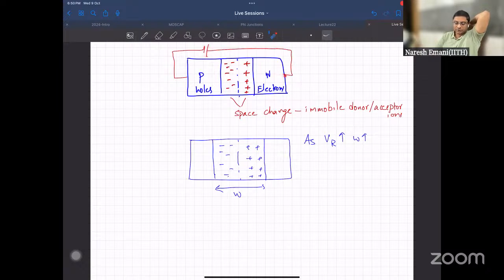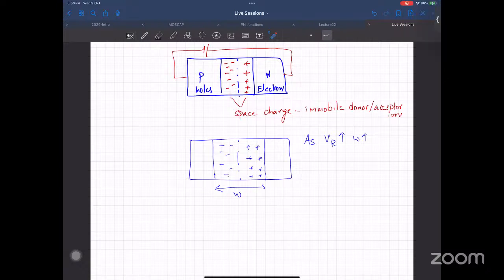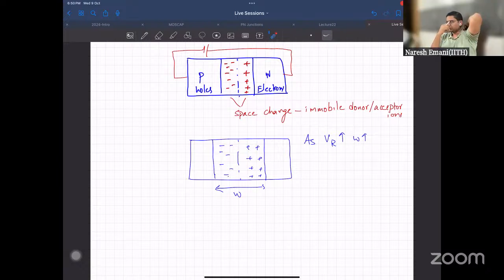So where will the electrons come from? Will they come from this edge here? No, because this is all a conductor, right? So essentially the electrons have to come from the edge of the depletion region. When they move out, they leave an additional amount of charge at the edge of the depletion region like this, and similarly another edge of charge. So the overall charge has increased. Yes, sir.